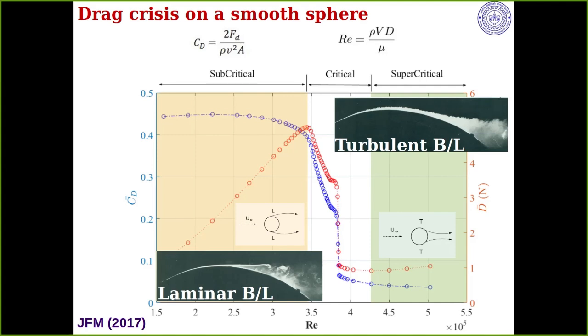That's why golf balls are different. If I could make the boundary layer turbulent at this lower speed, then I could get the ball with the same force to go much further. So this has been quite well known, and there's a lot of experiments people have done.